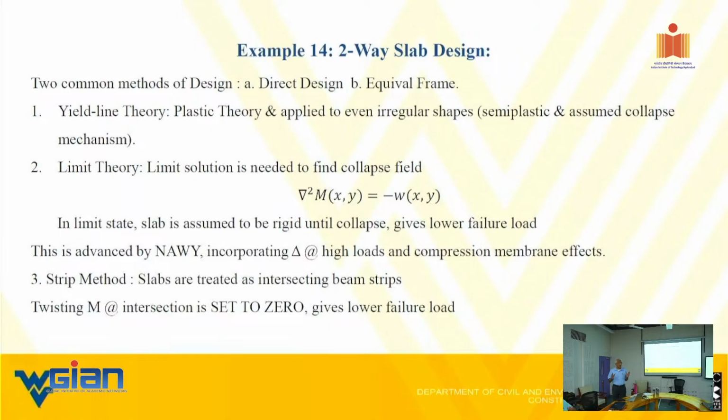We have seen concrete, maybe not after 28 days, after 35 days, it may not increase tremendously, but a 5%, 3% increase in concrete strength we did observe. So do not presume that concrete should degrade with time. Yes, there are scenarios under chemical plants or due to excessive cracking from corrosion, they degrade. I understand that. But material by and large does not degrade.